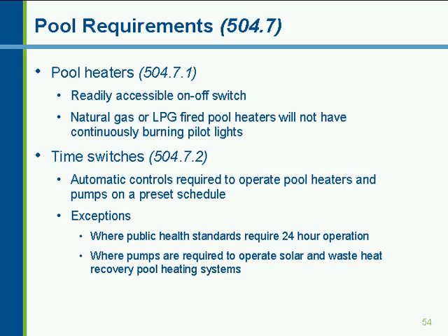And you must have a time switch or other automatic control to control the operation of that pool heater and pump on a preset schedule. There are some exceptions where public health standards require 24-hour operation. Then you don't need the time switch, or where you have a pump that's required to operate solar or waste heat recovery systems. Then you don't need the automatic controls as well.